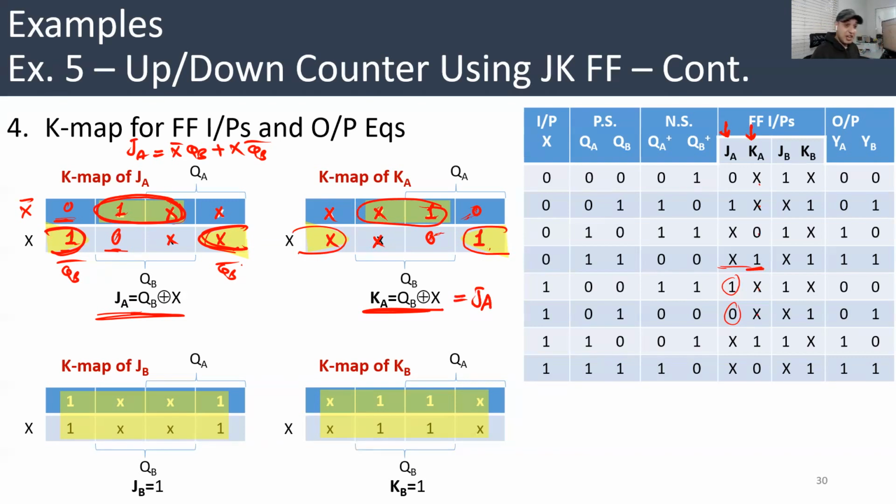JB, KB, this is really, really nice. The XOR here makes a great advantage for us. Look, if you consider all the X's are 1, then this is just one group, and JB will be just 1. Very optimal. This is the final optimal form, where JB is equal to a constant. There are no gates at all here.